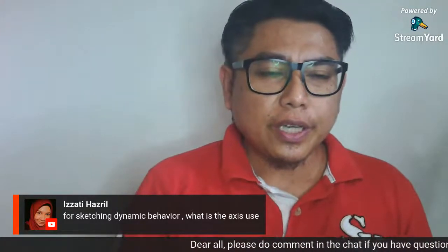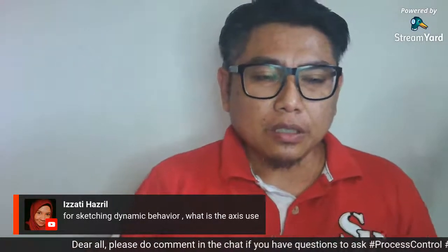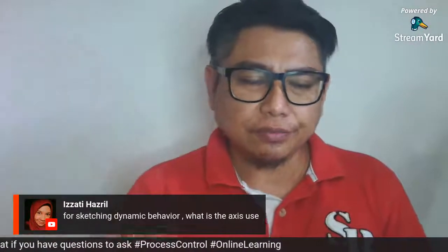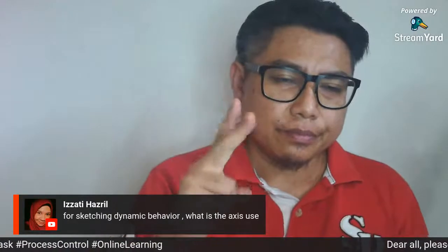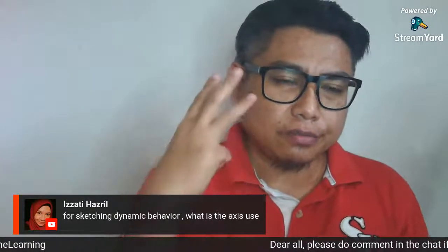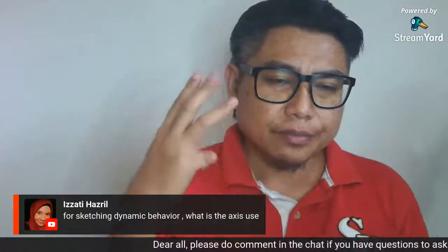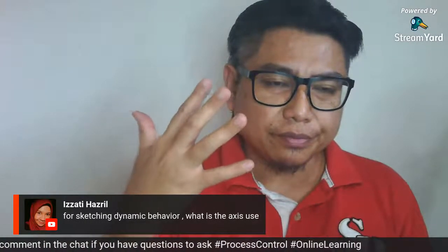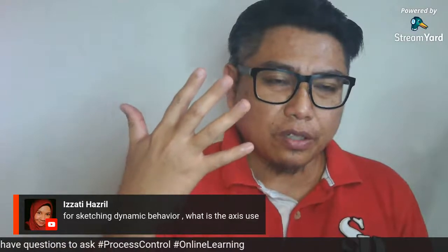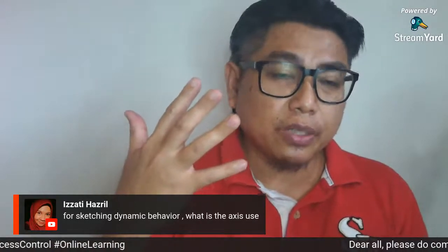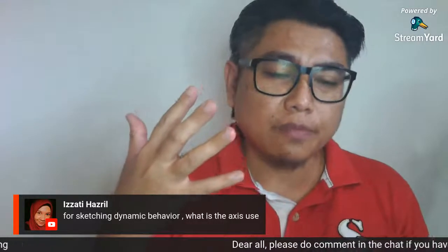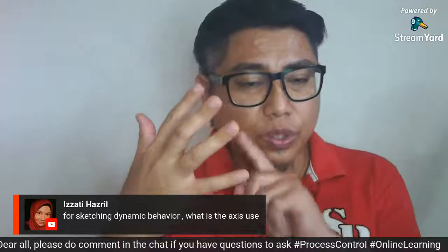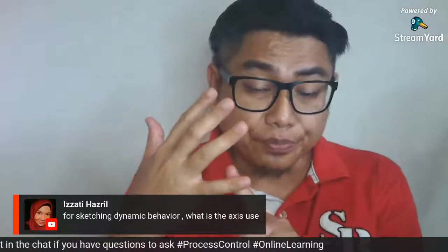All right. So make sure that all your tests basically cover these 5 things: the block diagram, the transfer functions, dynamic behavior, stability, and also tuning. Okay, all these 5 basically come from the block diagram. It is important for you to understand and master the block diagram.